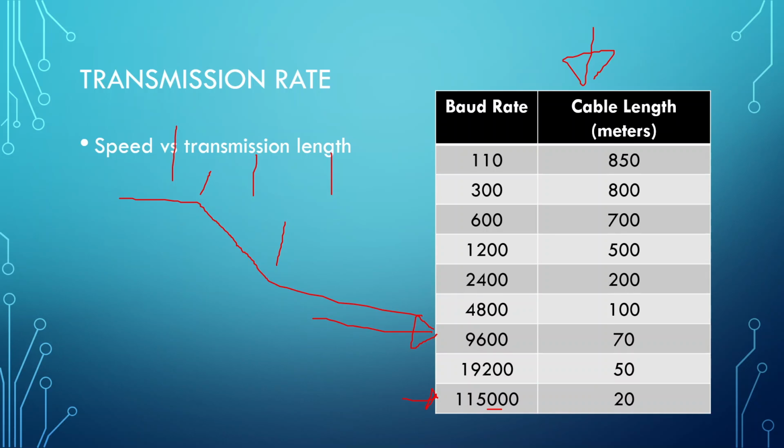So going back to my barcode scanner, if you plug it in and you're getting scrambled data, you probably have the wrong baud rate or other settings set. I actually find it really interesting.